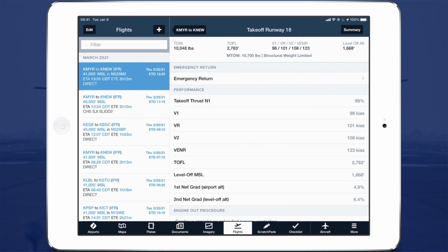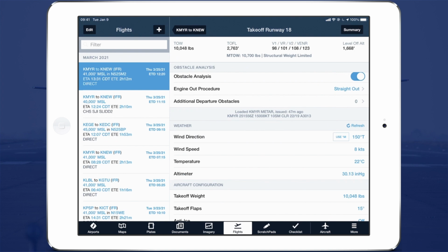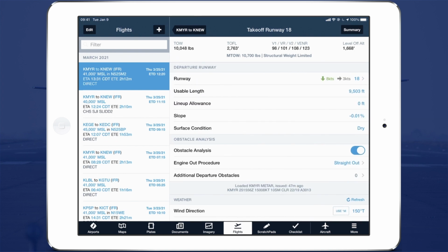That's a great point. And along those lines, something else to keep in mind is any runway behind you is kind of lost runway. So when you're standing on your brakes, you're at your brake release point. You want to be obviously at the end of the runway, the full length of the runway. We have here showing usable length, and this is the full length of the runway. By the way, we show usable length if all the declared distances are identical, which is in this case. If you select an airport and a runway where your TORA differs from your ASDA, we will list each one individually.